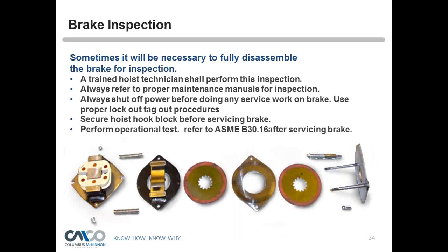So in conclusion, what did we learn today? One, a trained technician shall be doing the brake inspection. So if you haven't been properly trained or you're not comfortable with it, don't do them. Always refer to proper maintenance manuals, because as you've seen here, and I just gave a few examples, all those brakes were different. Even though they had the same function, they all had a little bit of a different way to set them, a little bit different way to look at them. So that's important that you get those maintenance manuals.